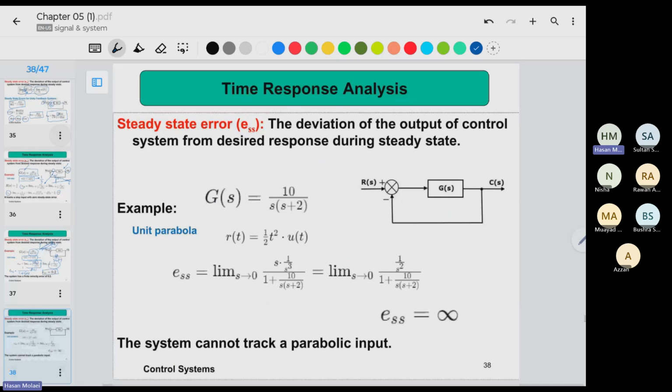And then what if we go one step further, integrating the ramp once more to get a parabolic input signal like this? We want to see how the system responds to this input. This input is a bit more difficult than the simple ramp because the input is kind of accelerating, right?